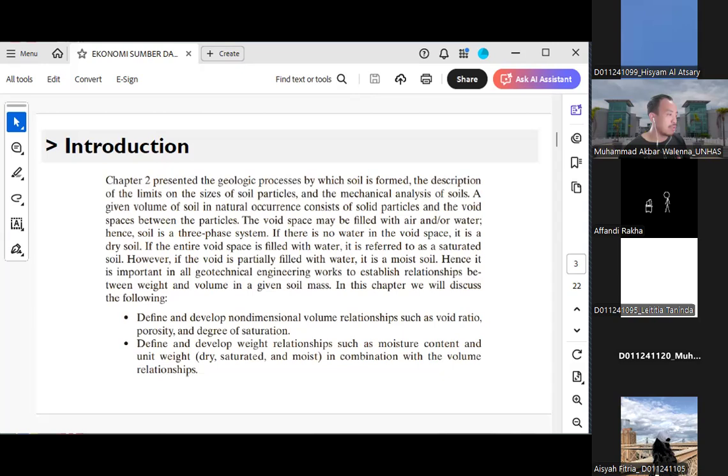Okay, meaning that you want the soil to withstand the potential loading or potential change of volume due to this application of load, in which it's really going to affect the overall stability of the soil. So that's why, given the examples and explanation I gave you before, saturated soil is a type of soil that we try to avoid, because saturated soil may become weak and fail during heavy rain or earthquake.